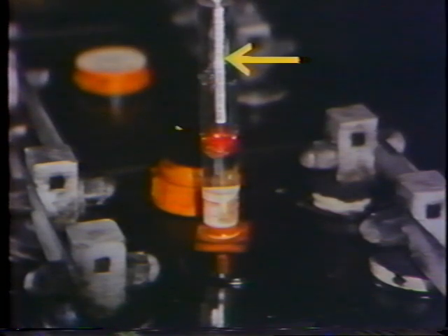Specific gravity is usually measured with a hydrometer, like this one. As you can see, it looks like a syringe. A sample of the electrolyte being tested is drawn up into this glass barrel. There's a float inside the barrel. The float is weighted at one end to keep it upright. The scale on the float typically reads from about 1.110 to about 1.300. We'll see why in a minute.